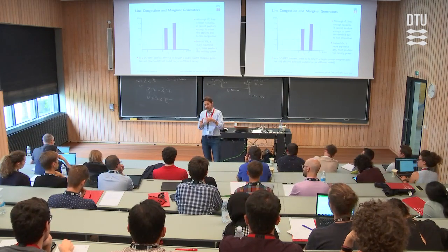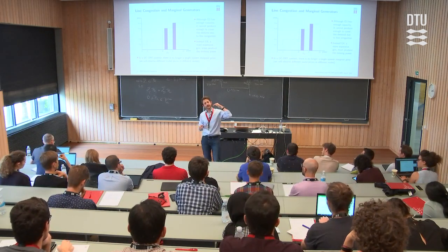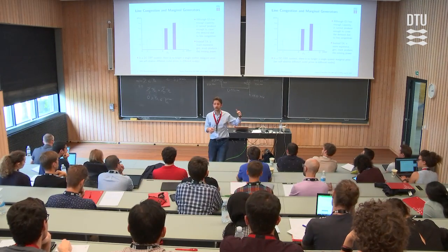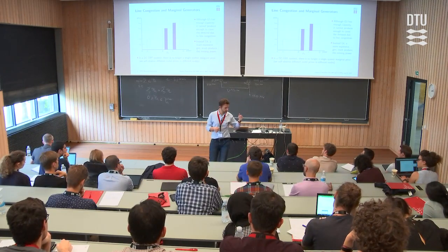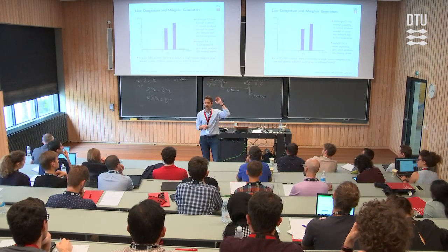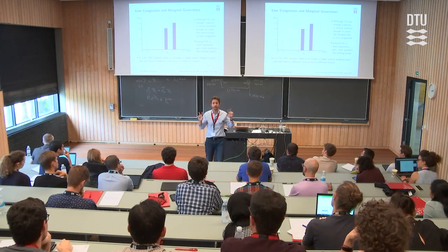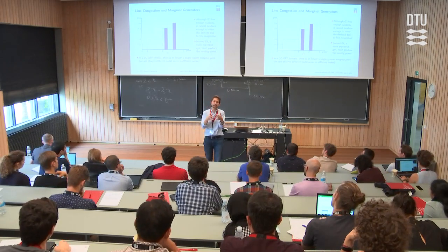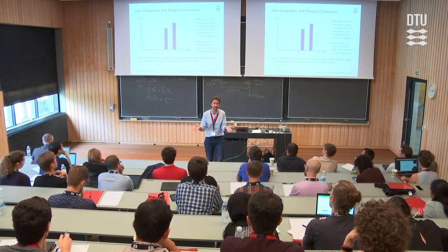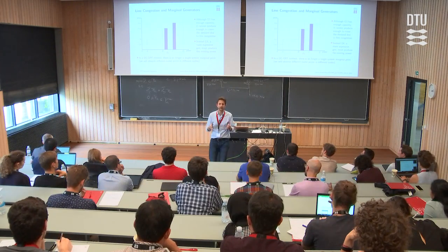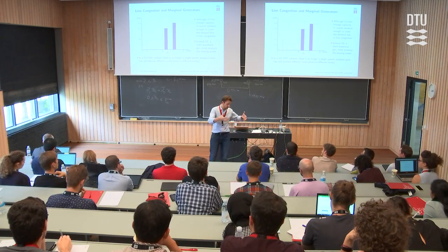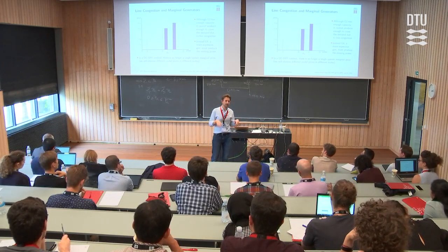losses, okay? And the way I do it is I bid with the highest possible price. So in Denmark, they bid, for example, 3,000 euros per megawatt hour. This is like the top they can bid because they don't want to distort the market, right? And at the end, they pay the most expensive price in Denmark for a generator, which might be 60 or 120 or whatever. But they don't want to distort the market. So I have now secured some power to cover my losses.